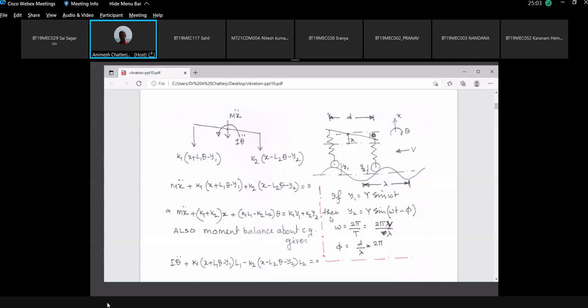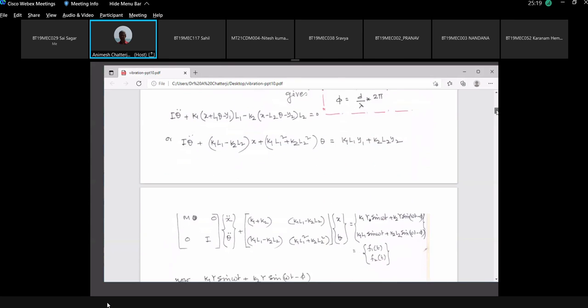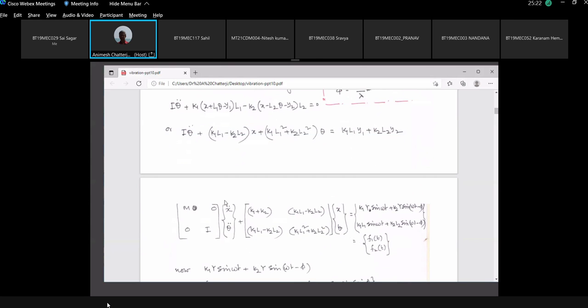So now, if we model, and these are the equation of motion, whether we are getting them using Lagrange or free body diagram, these are the equation of motion. And finally, I will show you the equation of motion only. Finally, this is how the equation of motion looks like in the form of matrix. So this is inertia matrix, this is stiffness matrix, and these are the excitation. Okay. So how we solve them, we will discuss. If we can solve them for, now why it is complicated? It is complicated because of two reasons.